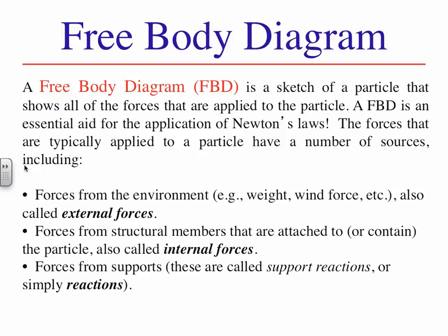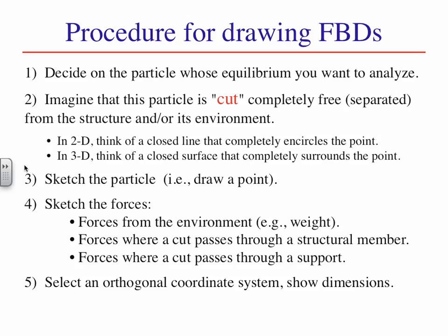Third, forces that arise from separating a particle from supports or points of anchorage to something massive. This could be a floor, ceiling, or wall if the particle is small, or the earth or soil if the object is large. These are called support reactions or just reactions. The procedure for drawing a free body diagram includes these steps.